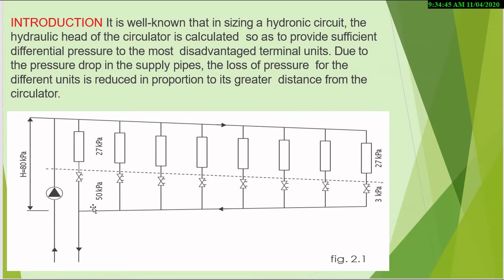Now, to solve such a widespread problem, it is necessary to increase the pressure drop of the terminal units. In other words, additional resistance is required. The value of this resistance must be both known and changeable. The ideal device for practicing this compensation is the balancing valve, which also allows to verify that the calibration is correct when reading the instantaneous flow rate.